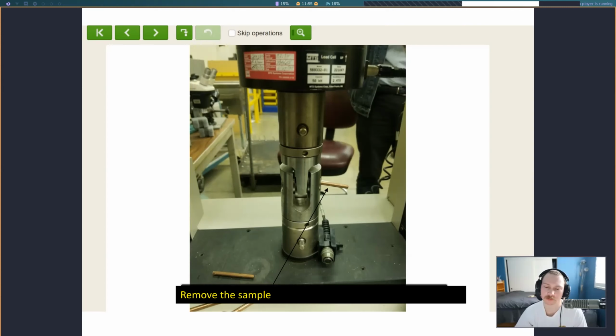And when our rod is placed inside of here, there is going to be bearing stress that's going to occur as well. Because we have a rod and there's some contact area that's shared between the rod and these 3 different metal discs that we saw earlier on. And because we have that shared area and there's a load being applied to that area, there's going to be bearing stress. So in the end, we're going to measure this length in the very center here. So we're looking at the bearing stress at that particular location in the center.